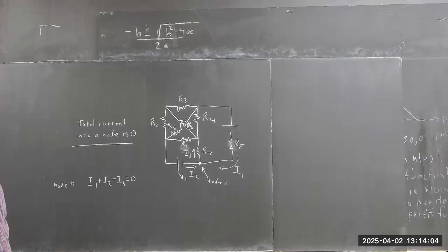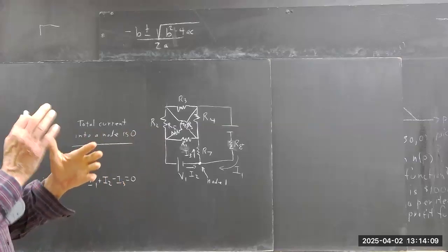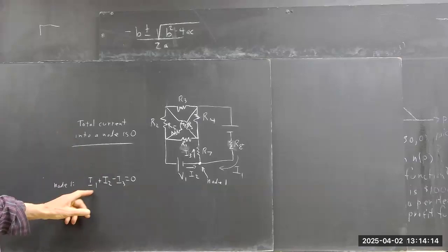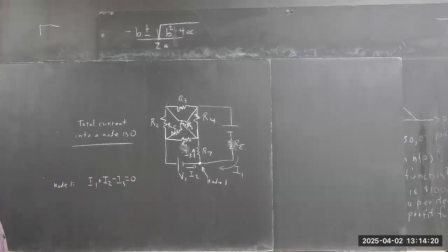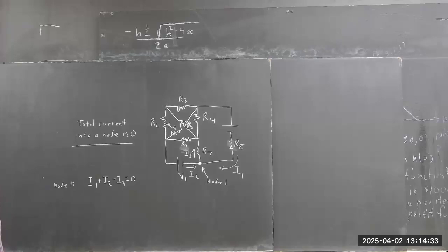Okay? And it's going to be a bunch of simultaneous equations, which is ordinarily a big problem, but there are going to be a lot of zeros in it. Like here, we've got I1 through I8. We've only got 3 of them here. Okay, that's going to make it simple. Now, if they get really complicated, it's just a matrix equation. You plug the coefficients of I into your matrix, press a button, and you get your solution. Okay, but it's surprisingly easy to do these by hand. It's pretty easy to see what you can eliminate, what you can't.